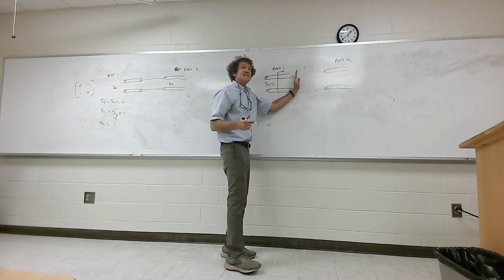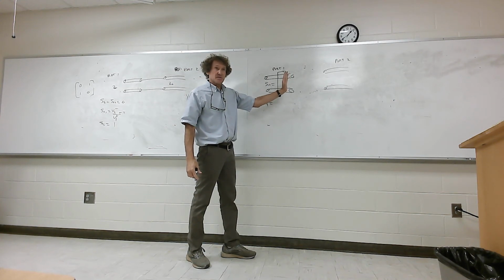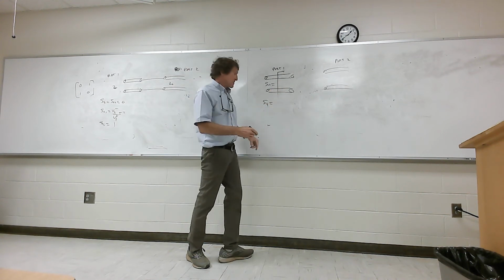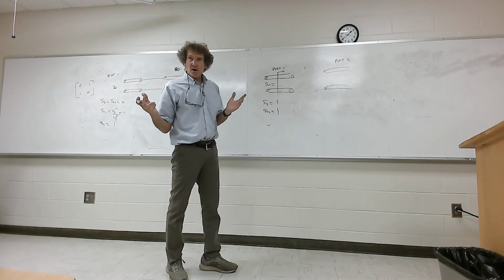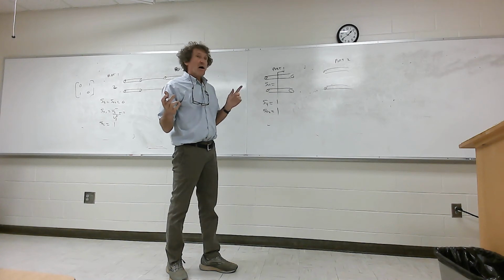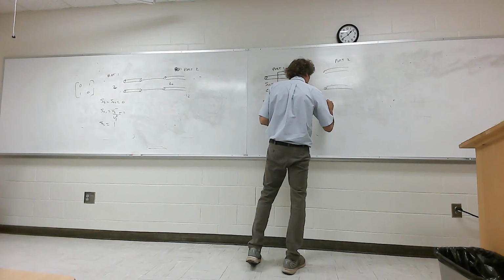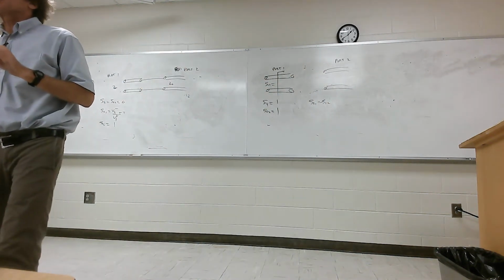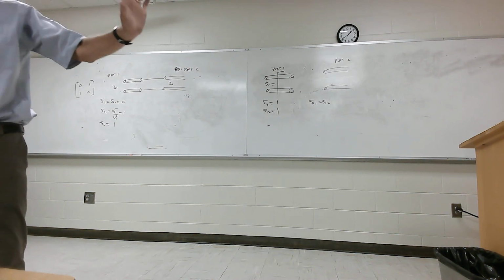It would be going into an open circuit. Just listen to me. An open circuit is infinite resistance, right? So infinity minus something finite over infinity plus something finite is 1. What is S22? The same thing, right? Arguments of symmetry. All right, now, what is S12 or S21? 0. It is 0 for one reason. There's no possible way any signal from port 1 can get to port 2. It's an open circuit. Y'all follow me? So that's another easy one.